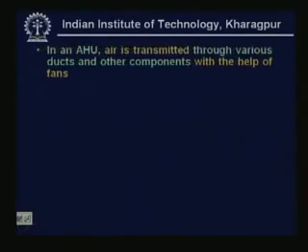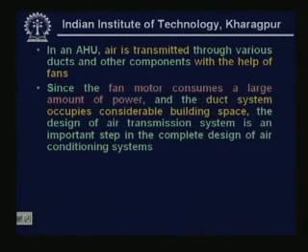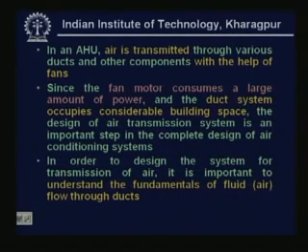In an AHU, air is transmitted through various ducts and other components with the help of fans. So, we need fans to distribute and transmit the air. Since the fan motor consumes a large amount of power and the duct system occupies considerable building space, the design of air transmission system is an important step in the complete design of air conditioning systems. In order to design the system for transmission of air, it is important to understand the fundamentals of fluid flow. Basically, here the fluid means air through ducts and various components of the duct.